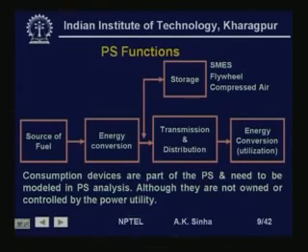There have been various methods of trying to store large amounts of energy, but as a percentage, this is almost negligible. Some of the storage devices used for large energy storage are superconducting magnetic energy storage. That is, we have a very large superconducting coil in which we can store energy as magnetic energy, and when we need it, we can draw it from that coil.